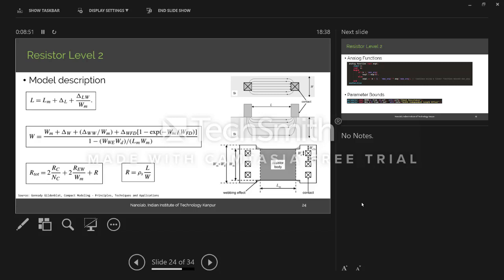So what we do is we always limit exponentials. In all compact models, you'll see exponentials are limited. You define a maximum number. Any argument which is passed to this exponential is limited to say 80 or something like that. We'll see it in the next example.